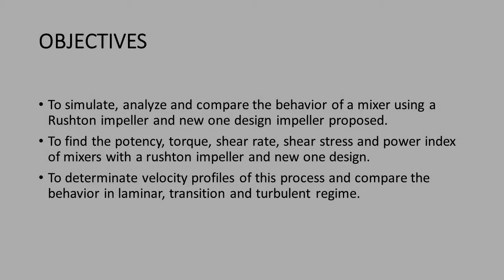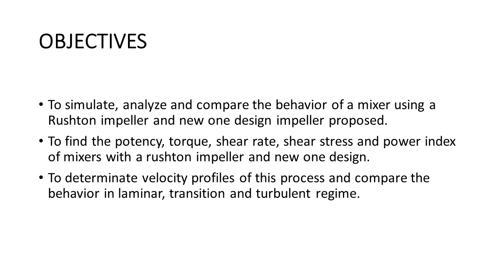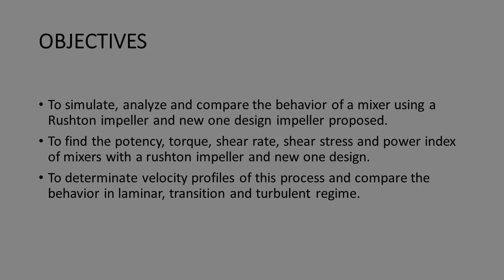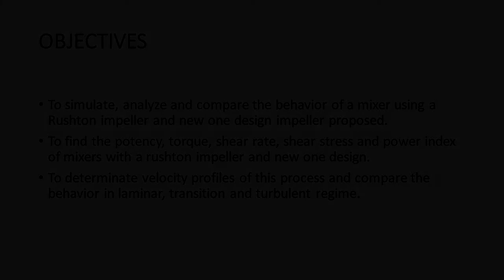The objectives are to generate a new impeller design and simulate both the new model and the Russian model, to find the power, torque, shear rate, shear stress, and power number of mixers with a Russian impeller and the new design, to determine velocity profiles of this process and compare the behavior in laminar, transition, and turbulent regime, to compare between impellers and recognize the behavior for each one.